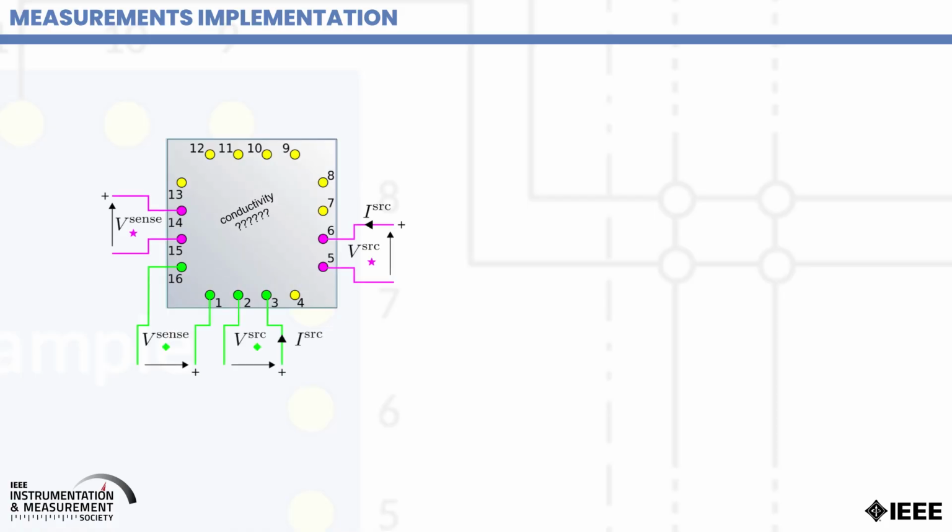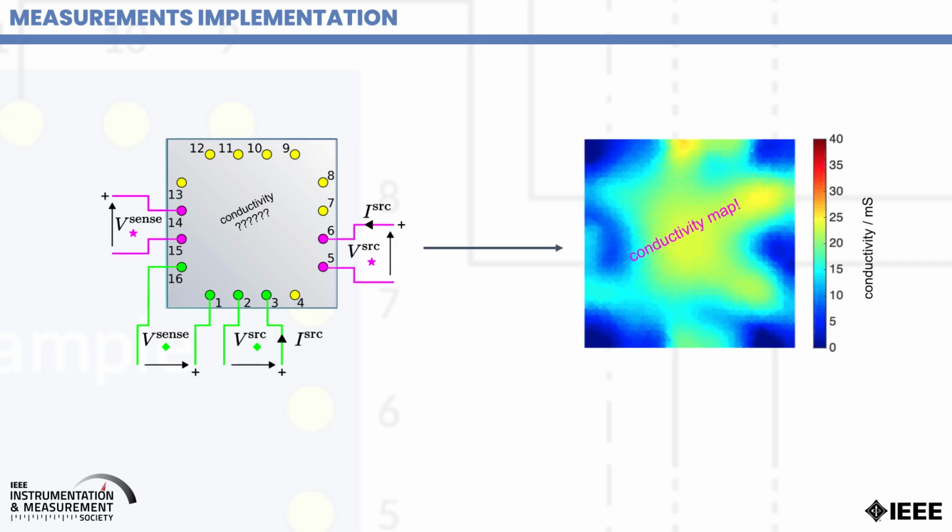Electrical resistance tomography requires a larger set, compared to the Van der Pauw method, of four-terminal resistance measurements. This redundant information acquired from the boundary of the sample allows you to retrieve not only a global estimation of the sample resistivity, but also, by means of numerical methods, which will be discussed in part 2 of this tutorial, to get insight of the conductivity distribution over the sample. Let's now take a look at some examples of results of electrical resistance tomography applied to thin film materials.